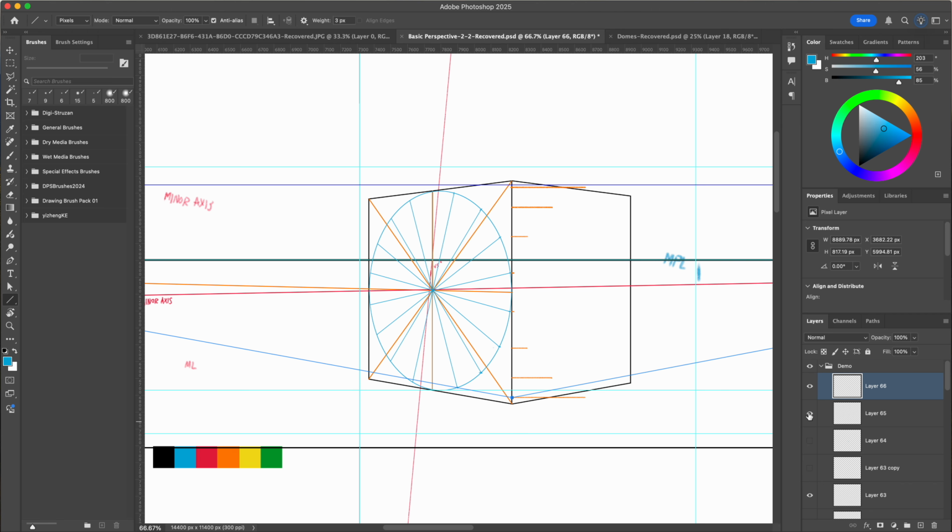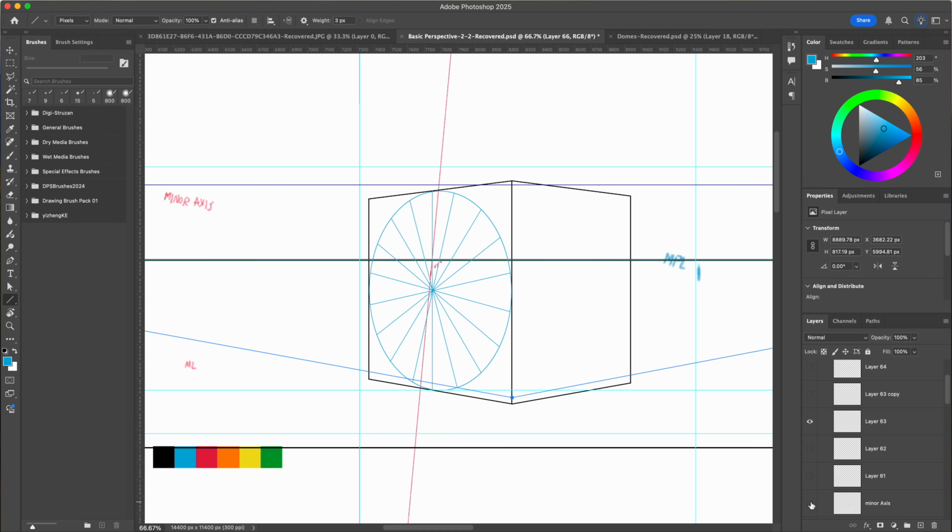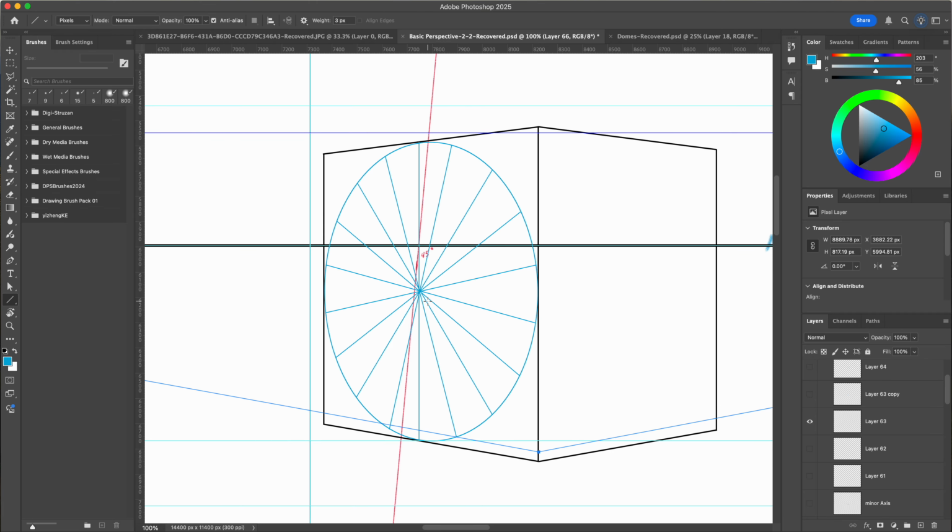All right, and okay, so I can hide those ticks. We don't need them anymore. We already projected them. Okay, that's our ellipse. Take our minor axes, we can hide it. So now all of these are divided evenly. They're all 20-degree slices around there, which is really, really nice. Okay, so I can do a lot with that now. And you can make it whatever degree you want. It's up to you. More slices, more lines. Less slices, less lines.